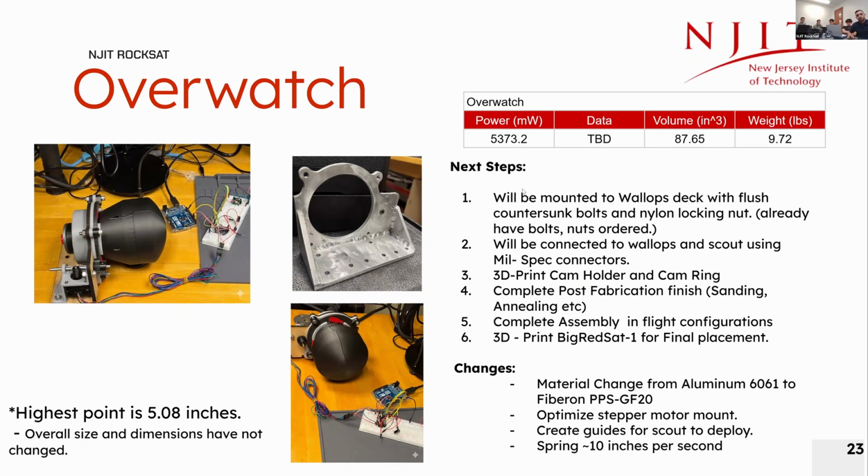All right, and then for Overwatch, our overall design specifications, the next steps for the test will be mounting to wall deck with flush countersunk bolts and nylon locking nuts. We already have the bolts. The nuts are ordered. They should have been here today, but they'll probably be here tomorrow. We'll connect to Wallops and Scout using mil-spec connectors.